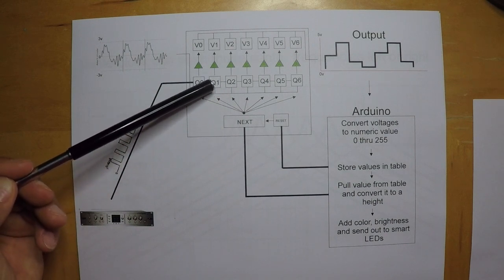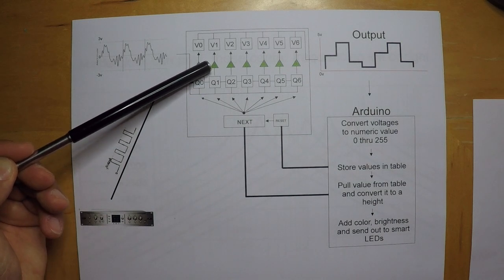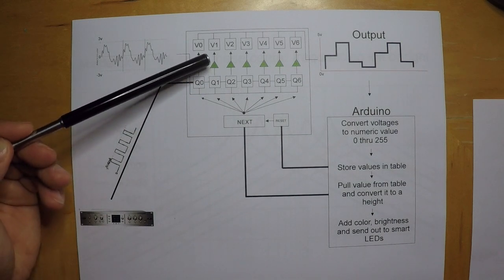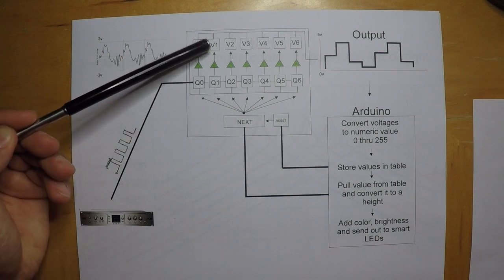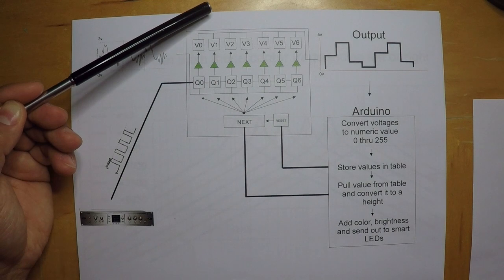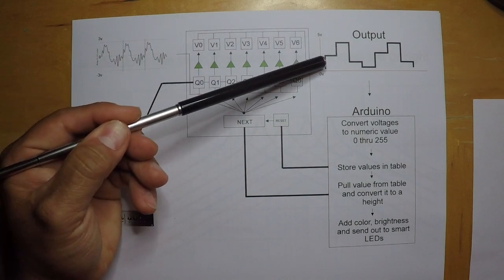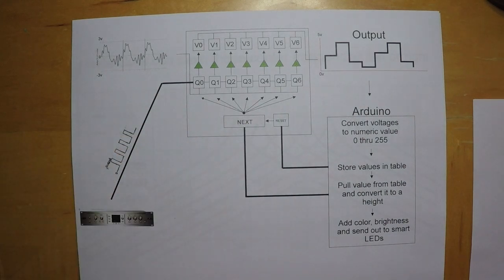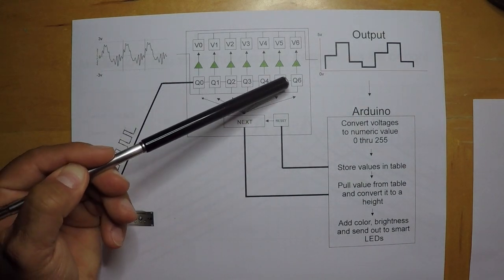Again, it sends those frequencies through some circuitry that analyzes and measures the loudness or amplitude of just these frequencies and converts it to a voltage from 0 to 5 volts. And then that voltage comes out and gets sent to the Arduino. And it does this again and again and again and again.